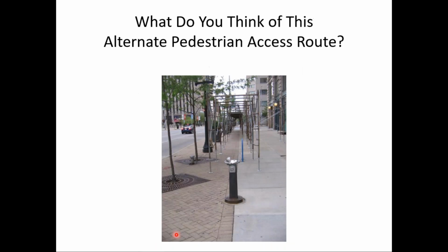How about this pedestrian access route? Took this a few years ago. I think that the work zone setup is not completed yet, at least I hope not, because it looked like people could get behind it here into this metal work, which again is a safety issue. So I hope when the job is done, and actually it should have been done, since I took this in the evening, should have been done probably before nightfall, is close this off with some sort of detectable barricade to prevent pedestrians just from getting into this area, period.